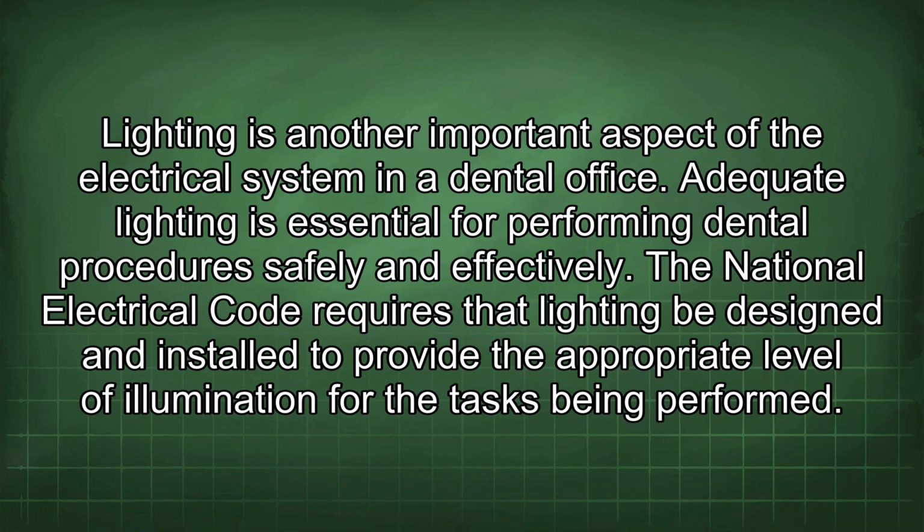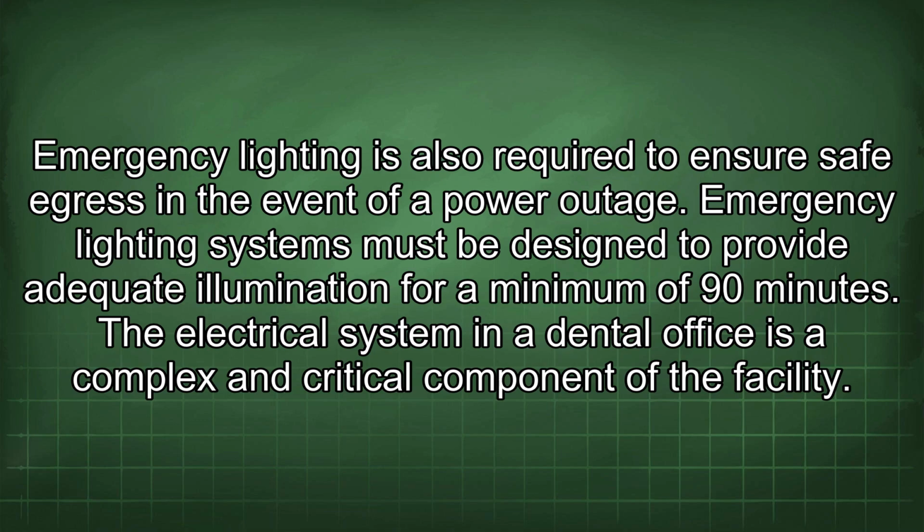Lighting is another important aspect of the electrical system in a dental office. Adequate lighting is essential for performing dental procedures safely and effectively. The National Electrical Code requires that lighting be designed and installed to provide the appropriate level of illumination for the tasks being performed. Emergency lighting is also required to ensure safe egress in the event of a power outage. Emergency lighting systems must be designed to provide adequate illumination for a minimum of 90 minutes.